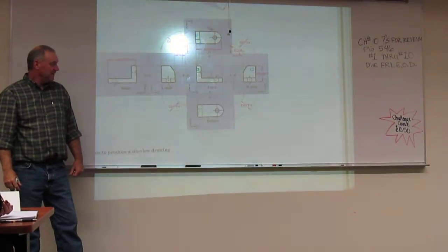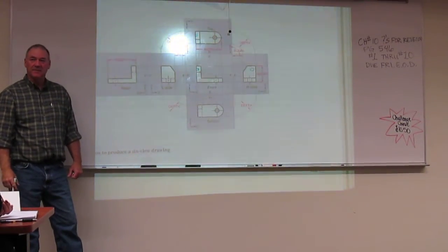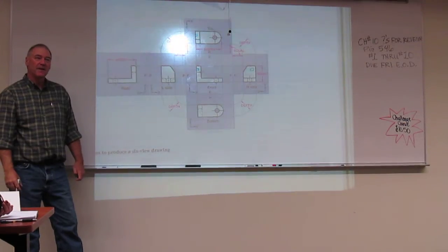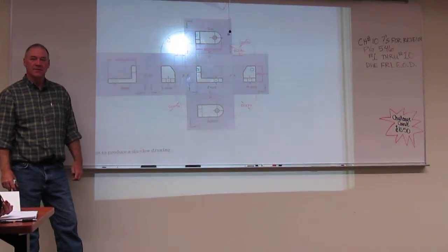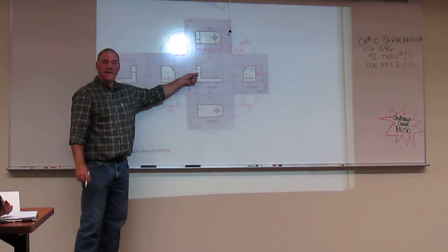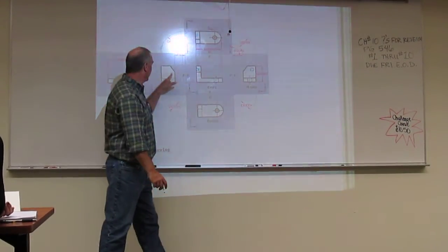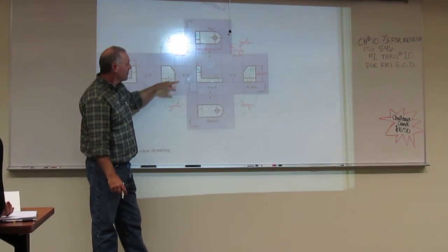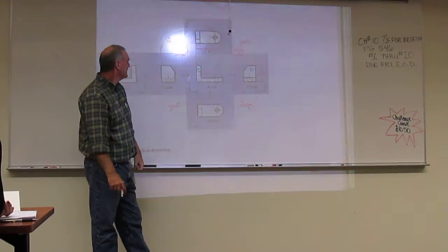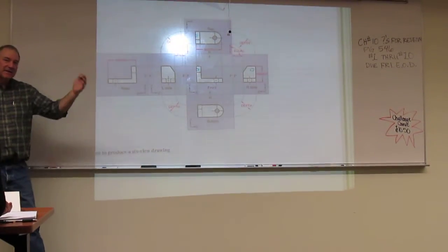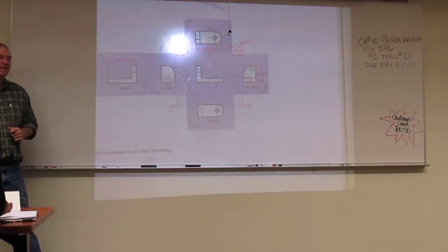On this one, since these are all hidden lines and I never see the circular view with an object line, I'd provide a left view. Just for that one feature right there. Now, I still have to provide this view for this, because if I go to the left, I see the left right there. Yeah, that's what I was wondering. Yeah, you're going to get a conundrum here.